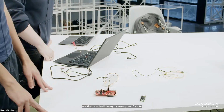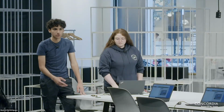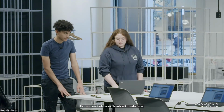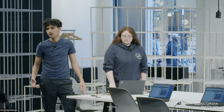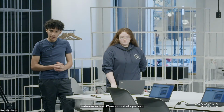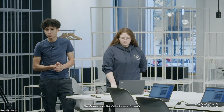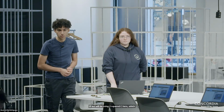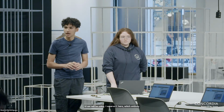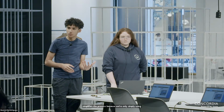Now, for communication between two boards, which is what we're trying to do, we have different communication protocols. There's major ones. There's like I2C. There's SPI. There's UART. We will be using I2C here, which entirely simplifies the process because we're simply using two wires. One is the clock line, which is called the SCL, and one is the SDA line, which is the data line. So you can understand that there's a clock line.